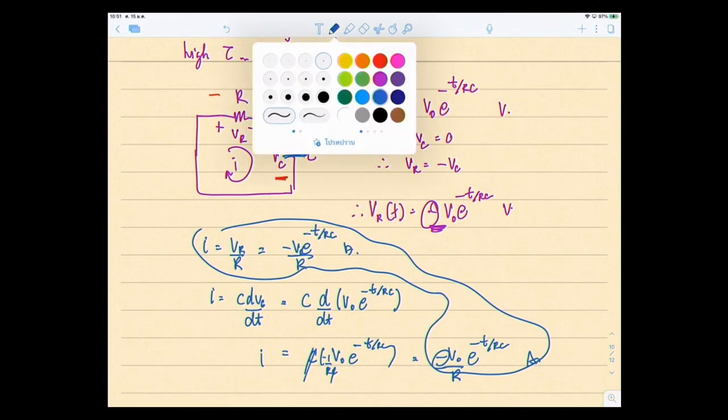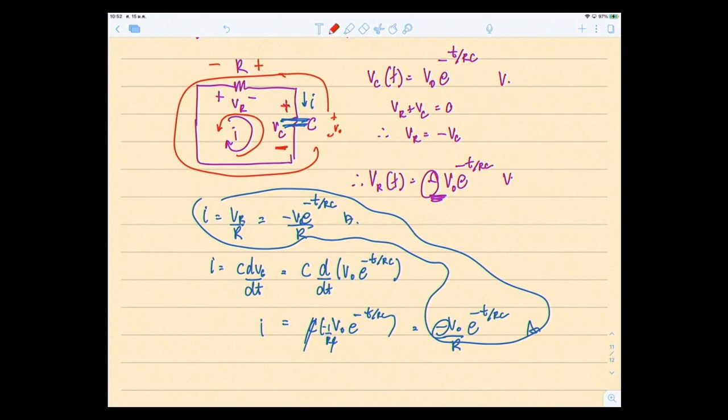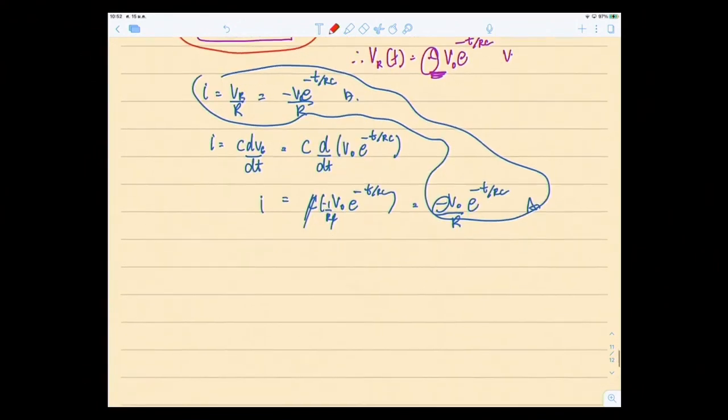It means that what you have assigned, if you draw this, actually goes in the opposite direction, your current. What's going on here is that your VC starts with V naught, so it becomes like a source in this circuit, and it generates the current I coming out like this, feeding it through R, and then going back like this. So it's very important to watch the sign, so be careful. All right. Let's see an example.